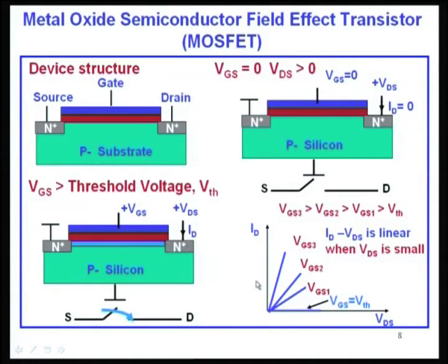You can control the drain current by changing the gate voltage and the drain voltage. Okay. Now, let us see what happens if I keep on increasing the voltage. If I keep on increasing further, notice when the current flows from drain to source, because of charge flow in this direction, there is a voltage drop along this channel, and sufficient electrons will not be created unless the gate voltage VGS is above a certain voltage called threshold voltage.